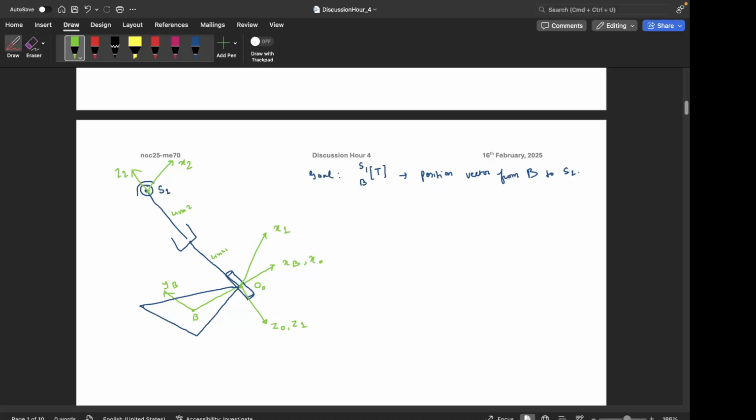Since we need to find the position of the center of the spherical joint, and the spherical joint has three revolute axes intersecting there, we need not assign any further frames in order to find the position of the spherical joint. So let's again re-understand the frame assignment process. xb and yb are the frame attached to the centroid of the base link. Then there is a frame attached at the origin of the revolute joint, coincident with the frame that is rotating with the revolute joint.